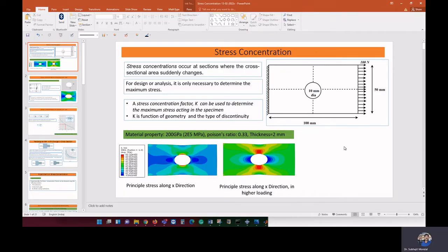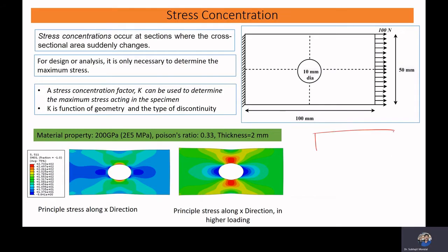In such cases, we observe that failure of the material occurs either in this middle zone or near the support. In many cases you will observe failure near the support because stress is high here. In such cases, we reject the sample and consider those samples which fail in this zone, so that we make sure the stress is uniform here, and whatever data we are measuring is due to the uniform stress in this zone.